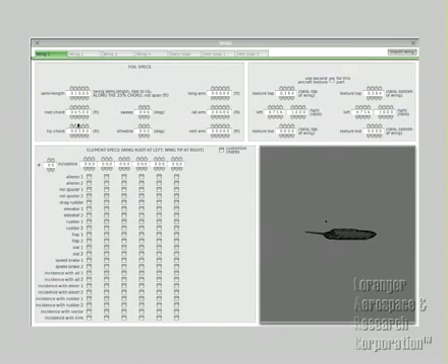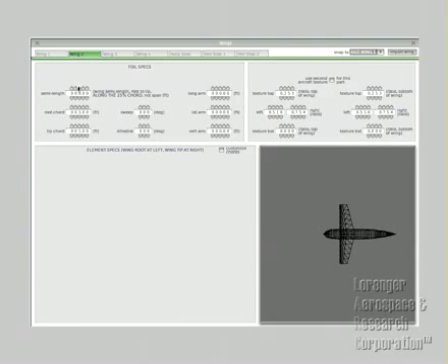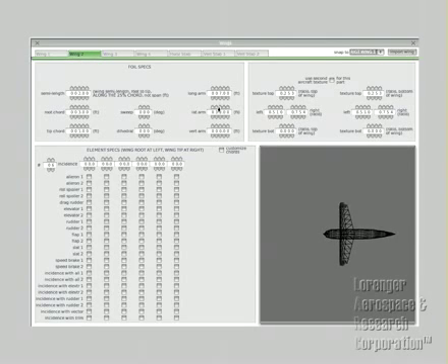The next step is to add wings, and in PlaneMaker you can do different things up the wazoo with wings. Right here we're adding the change in the root and tip chord, the dihedral, sweep, length, and overall positioning of the wing. We can always change this later. Just always remember, it's good to get a basic start. Get a basic shape that flies. It's all that matters here.